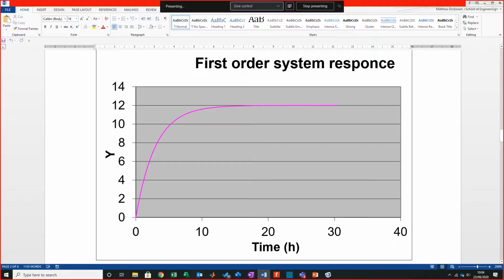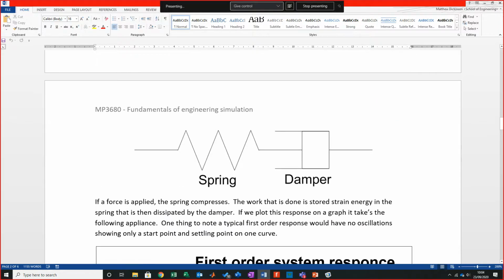Now that typical idea is because there is a spring and a damper sitting in it. The spring, as most of you will well know, is an energy storage methodology. If I pull it or if I compress it, I can put energy into it and it will be stored within it. Once it's released, it will try to return back to its normal state. However, if we want to control that return, we can put in a damper. That damper will dissipate that energy, so I can choose how it's passed between those 2 points as it's running. A typical drawing for it would look like that.